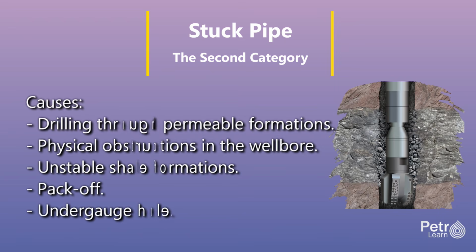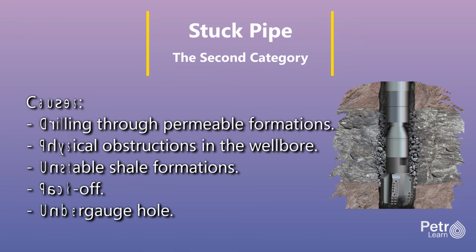On the other hand, mechanical sticking occurs when physical obstructions in the wellbore prevent the drill string from moving freely. One common cause is poor hole cleaning, where cuttings or cavings accumulate and form a bridge above the drill string, blocking movement.